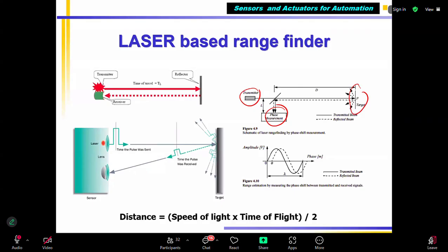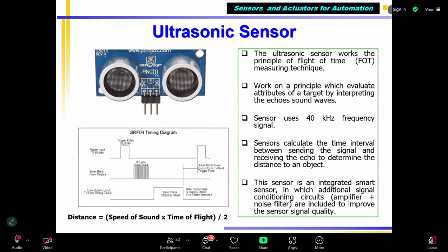Okay, shall I go to the next sensor? Okay, next, yes. The next one is the ultrasonic range sensor. Third type. Why am I talking about range sensors? In an autonomous vehicle, we need this. Measuring the distance between your vehicle and the one in front, back, side, all this will be long range, short range, parking. Parking will use ultrasound or infrared.